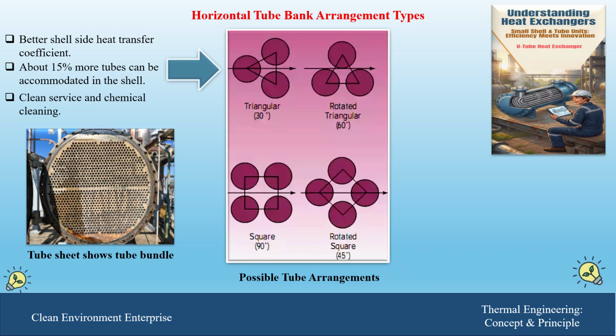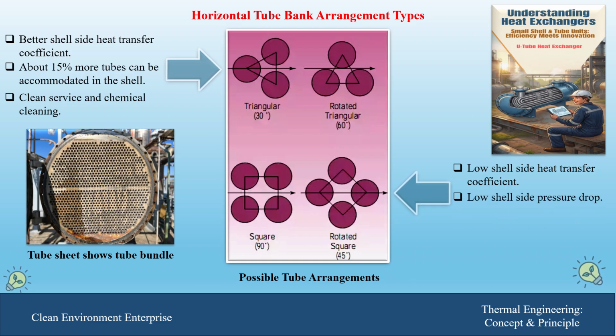And this type usually has a low shell side heat transfer coefficient, and of course that will be accompanied by a lower pressure drop on the shell side, and mechanical or chemical cleaning can be used.